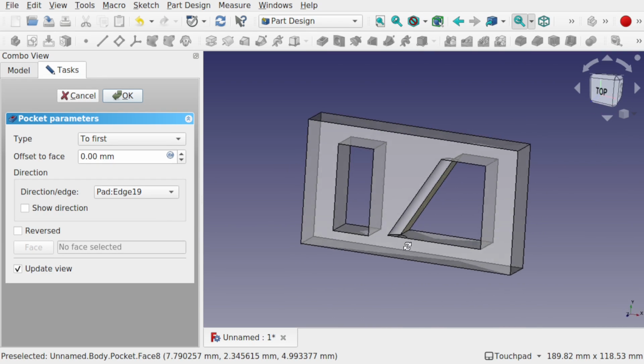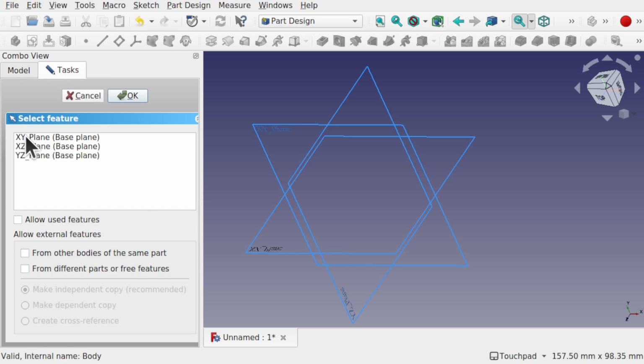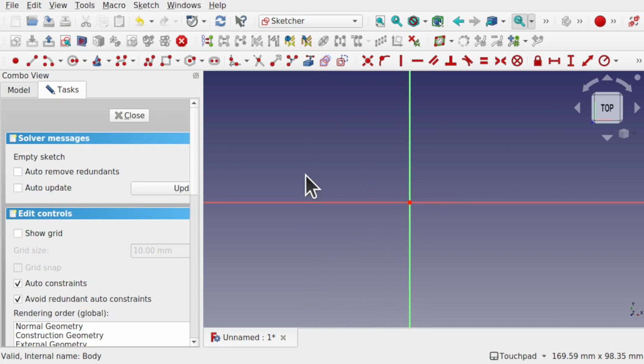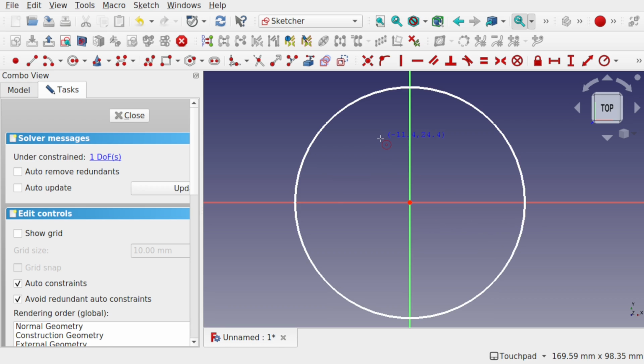as reference. So for a practical demonstration, we'll come back into the part design, and we're going to be looking at a way of using those pocket options, those pocket types in there. So I can create a new body and create a new sketch. Going along the XY plane and hitting OK, looking down from the top. And I'm going to create a simple disc in here, and I'm going to put some geometry in here that will allow me to attach this to a wall over a screw or a large headed nail, so it's locked in so it doesn't come off the wall. You see these on fire alarms and boxes that attach the wall.